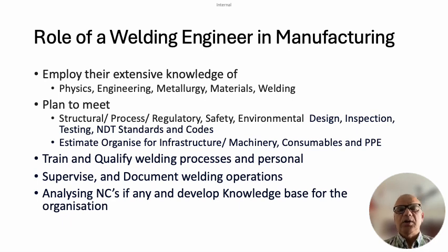If not, the non-conformance is required to be reported, and the repair activities as permissible by codes and standards are carried out, and then you document all these things.